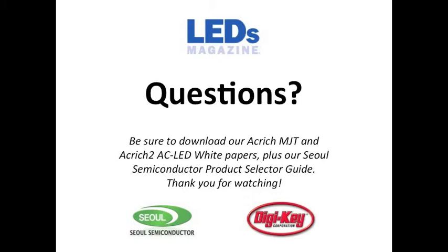You're actually growing it that way. So it's one monolithic chip with multiple chips on it, and there is no singulation of the die. The epitaxial is done that way, and then during etch and lithography is when you actually create that MJT technology. Correct. And you can do multiple series, multiple parallel, so depending on what you're looking at, multiple voltages for different types of LEDs. Yes. But you believe that's a more reliable, more robust way to get to a multi-emitter type package? Yes, we do.